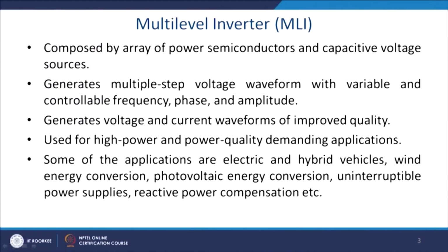So, the multi-level inverter is essentially composed of an array of power semiconductors and capacitor voltage sources. The array of power semiconductors is generally the diode clamp multi-level inverter, we shall see a little later, and the capacitor voltage sources are the capacitor multi-level inverter.